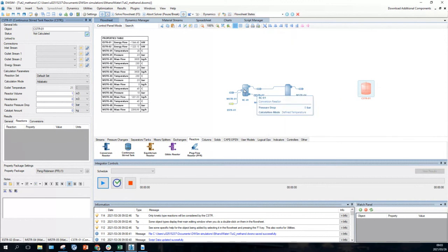And that's why I'm always going to recommend, when you're doing DWSim, you use conversion reactors, and you set your conversion to be less than at least what the Gibbs reactor would predict. In other words, less than equilibrium conversion. And then you can go and design your reactor using Python or whatever you choose.